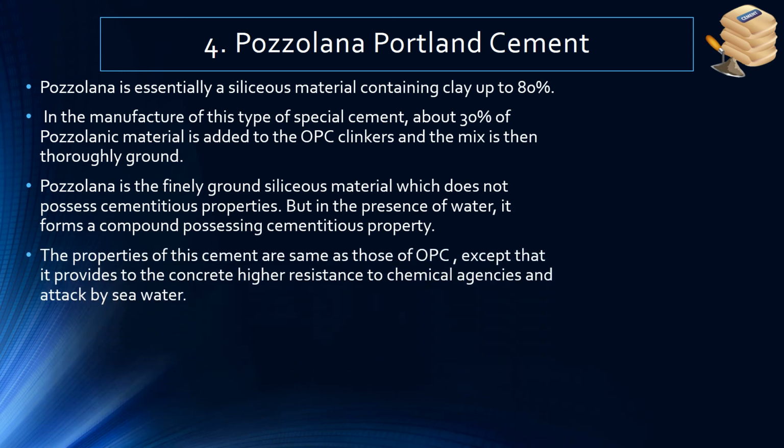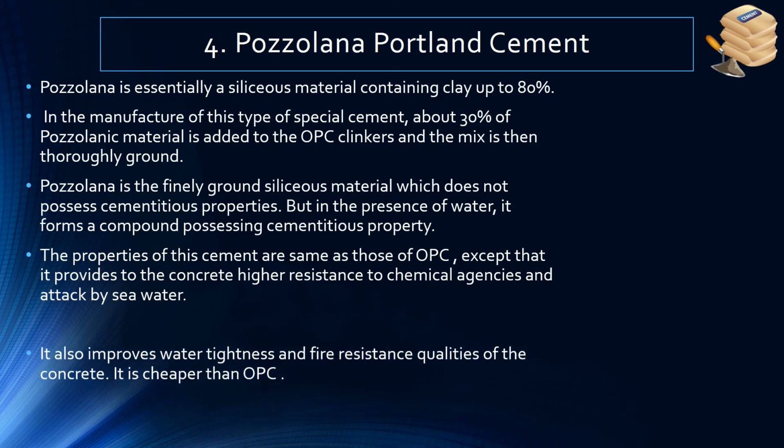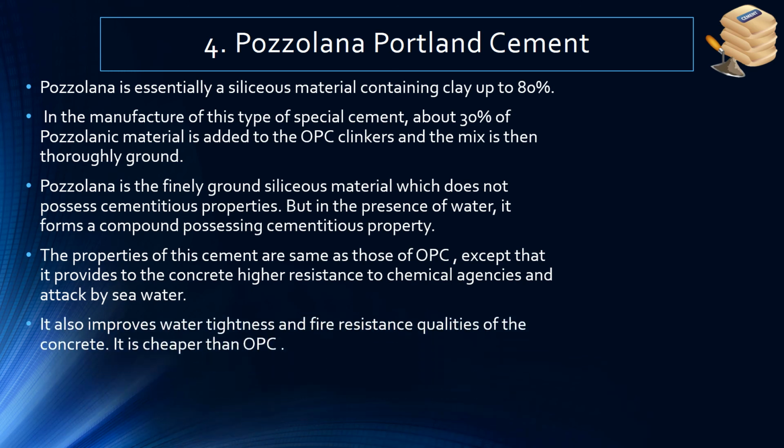The properties of this cement are the same as those of OPC, except that it provides the concrete with high resistance to chemical attack and attack by seawater. It also improves water tightness and fire resistance qualities of the concrete, and it is cheaper than OPC.